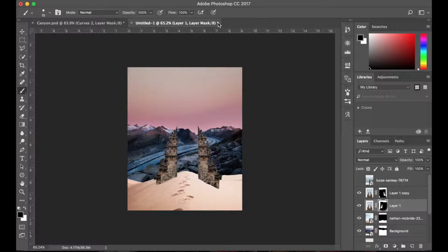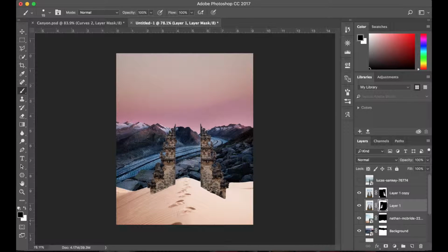So I've taught you guys how you can cut out the sky, how you can replace it and put this little glow, add some light into it, and then how you can cut things out and blend things in a little bit better. So that's been today's video. It's been a little bit more about blending things in, and what I'm going to do now is finally show you guys how you can add some lighting effects. So the first of the 2 techniques I'm going to show you is using the dodge and burn tool.